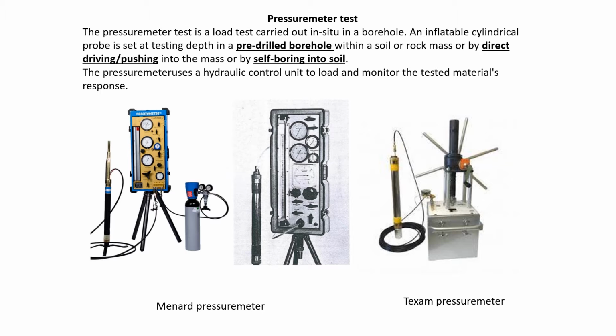So what is the pressuremeter test? The pressuremeter test is designed, and the pressuremeter equipment is made, to assess compressibility of the soils, modulus of the soils, and definitely how you carry out the pressuremeter test. You make the hole, place your probe, inflate your probe, and look for the stress-strain relationship on this curve.